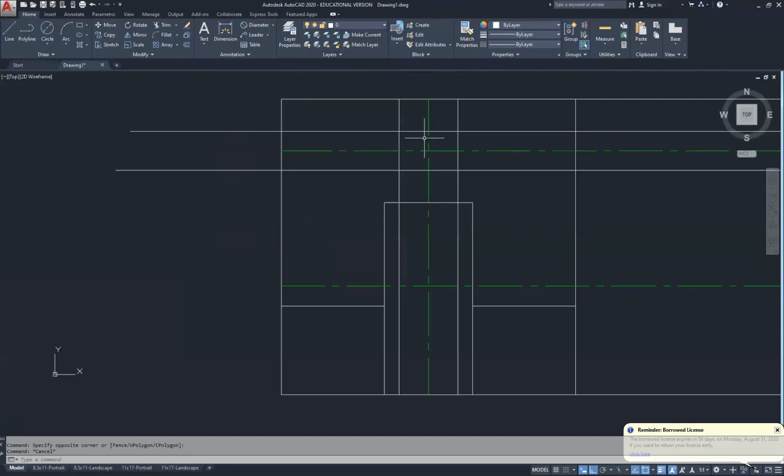And we can see this little rectangle here. This is where the shortened circle is going to go, which is an ellipse. So, in using the ellipse command, we're going to use this icon right here. I'm going to change it to axis end.